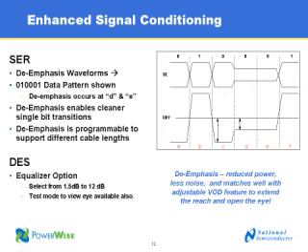If we refer to the letters at the bottom, we'll just walk through the transitions here, looking at the single-ended signal at the top and the differential signal at the bottom. So for the first transition, first signal, we're sending a 0. We're swinging to the full differential swing. Again, a single 1, we're going to the full differential. Then we have a series of zeros in C, D, and E time frames. We're swinging the full swing on the first 0, but then you'll notice that we back off. This is where we're using de-emphasis.